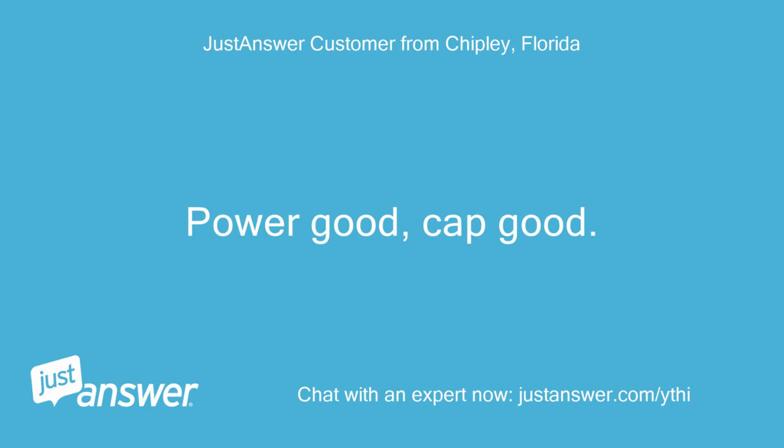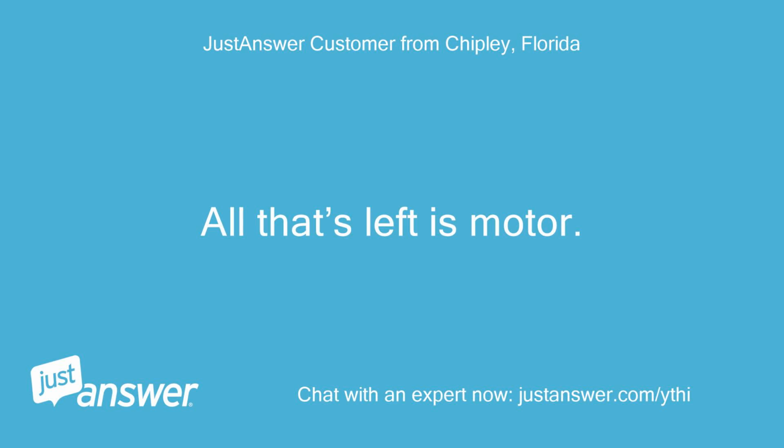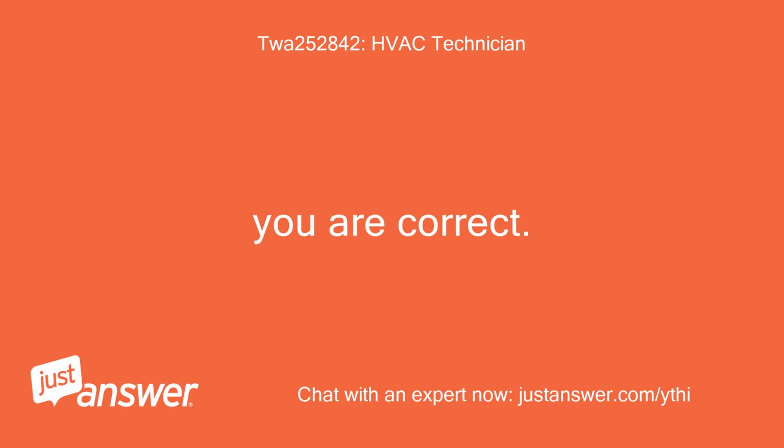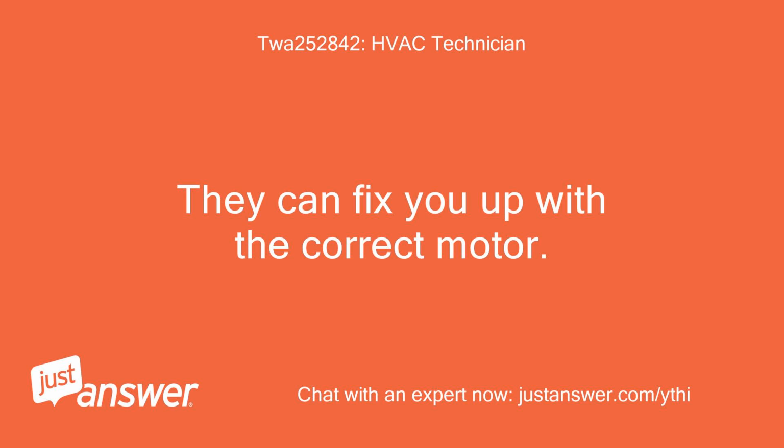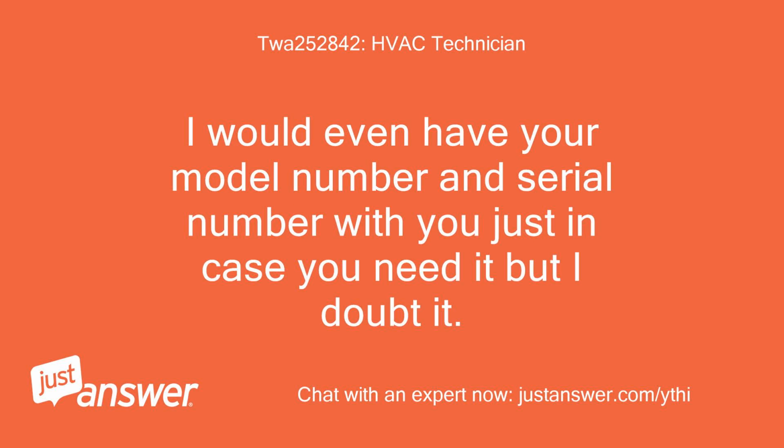Power good, cap good. All that's left is motor. You are correct. Since you have a Goodman piece of equipment, Johnston Supply, a nationwide vendor, carries Goodman. They can fix you up with the correct motor. I would even have your model number and serial number with you just in case you need it, but I doubt it.